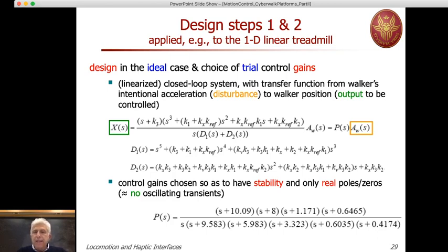So once we linearize this and look at the mapping, we are already a closed loop system, so our target is to bring the actual position to a certain location in response to a disturbance. So we are looking at the disturbance input to controlled output transfer function. This transfer function takes on quite a complex format. There's a sum of two terms at the denominator, but the denominator in fact is a fifth order polynomial. The numerator is a fourth order polynomial.